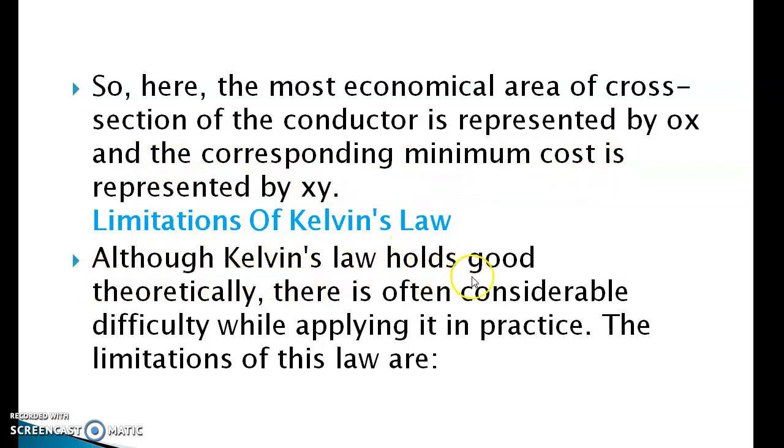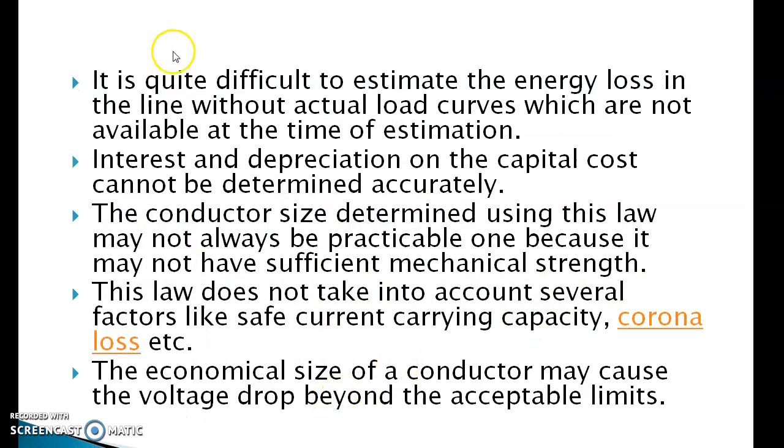Limitation of Kelvin's law. Although Kelvin's law holds good theoretically, there are often considerable difficulties while applying it in practice. The limitations of this law are: it is quite difficult to estimate the energy loss in the line without actual load curves, which are not available at the time of estimation. Interest and depreciation on the capital cost cannot be determined accurately.